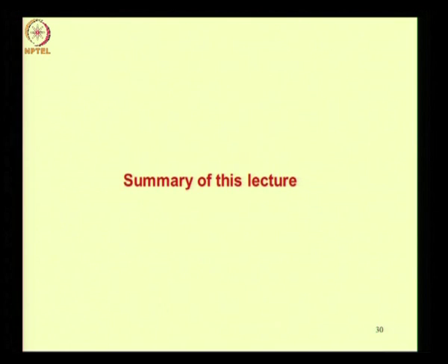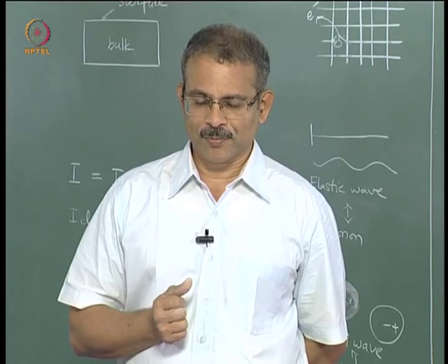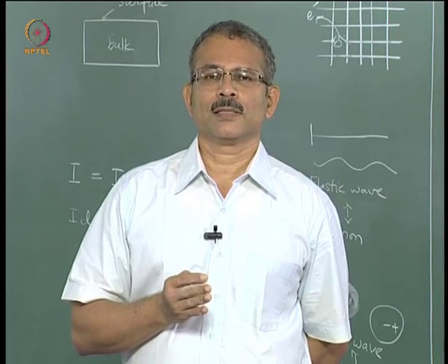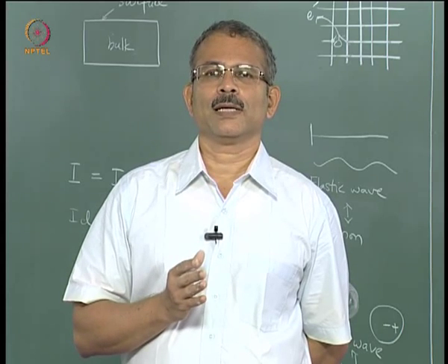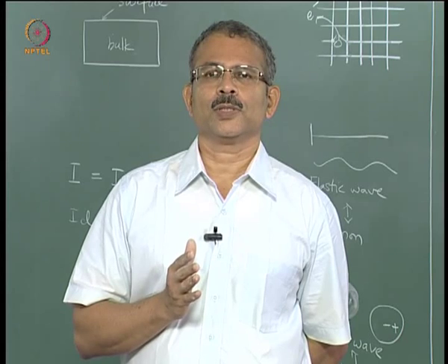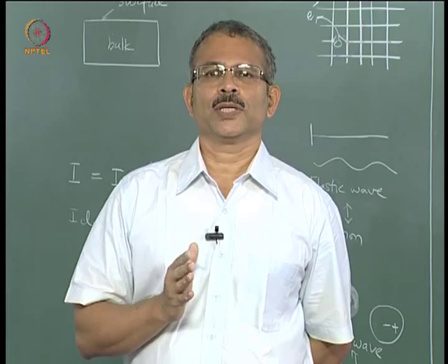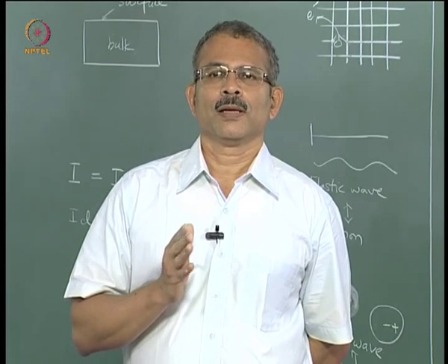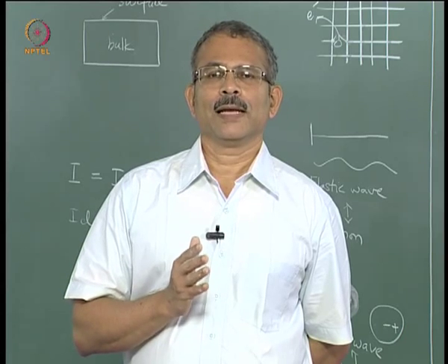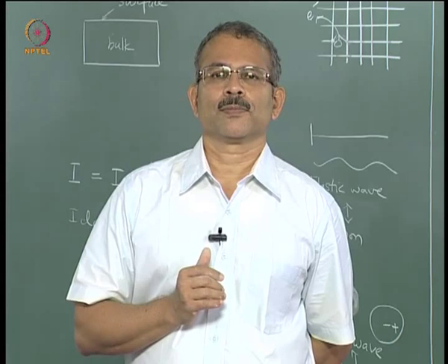We are towards the end of this lecture, so let us make a summary of the important points. In this lecture we first pointed out the phenomena of carrier transport, particularly semi-classical carrier transport, that we want to explain. These phenomena were drift, diffusion, thermoelectric current, then velocity saturation and negative resistance, then velocity overshoot effects and ballistic transport.